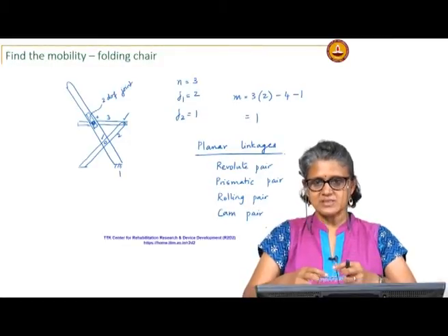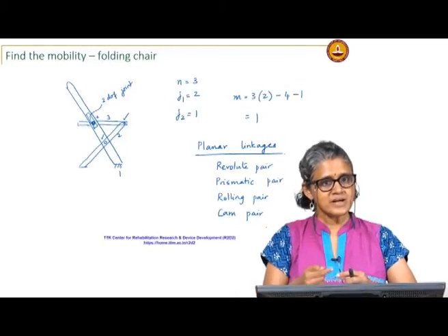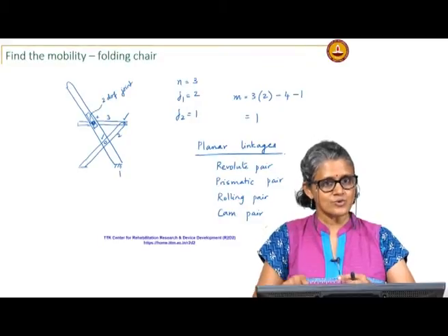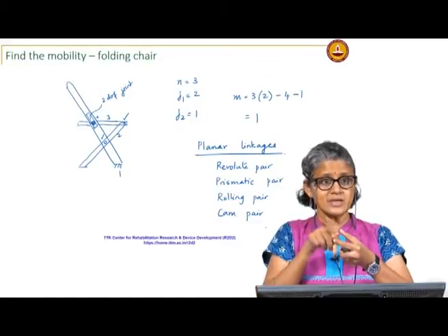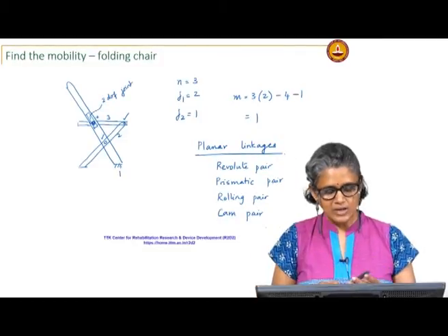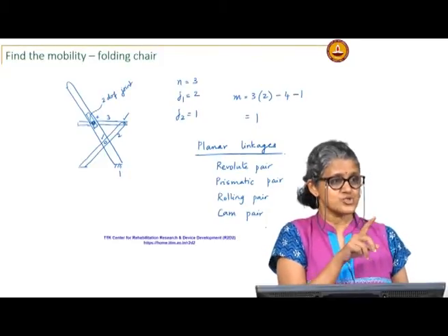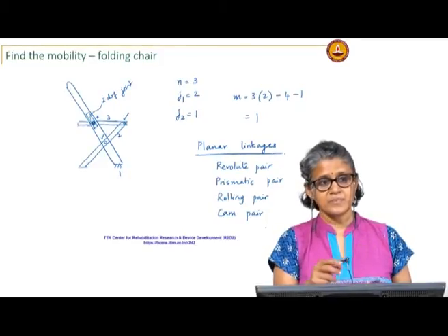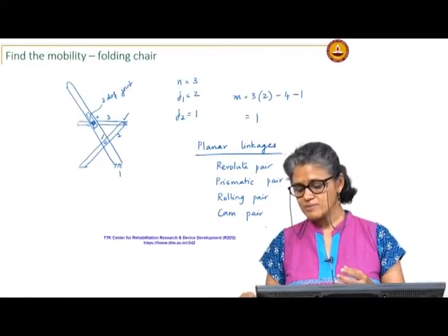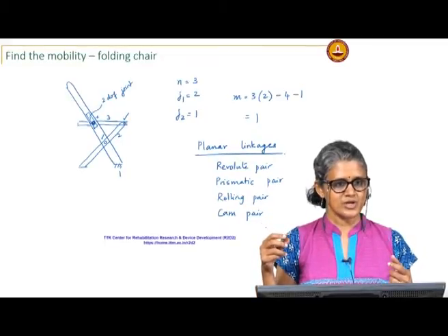Okay. So, if I place the screw joint like this, I am not going to be able to see the translation, I can only see the rotation. Similarly, if I am looking at only the translation, I can't see the rotation from that same plane of observation, so screw joints are not part of a planar mechanism. You will find screw joints in many applications, but they will be used for things like a one time adjustment. So, if you look at a pair of pliers, cutting pliers, right. Many of them will have a screw joint.